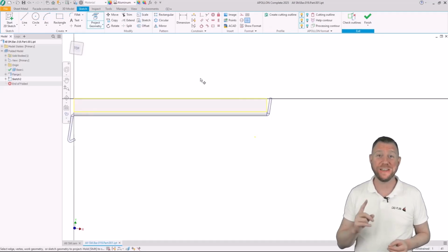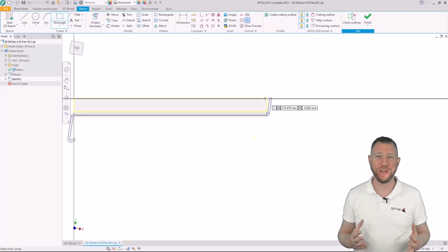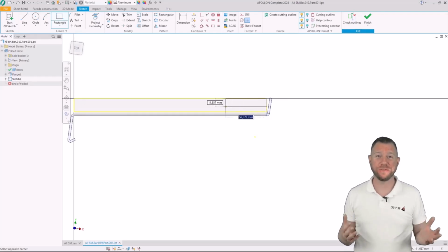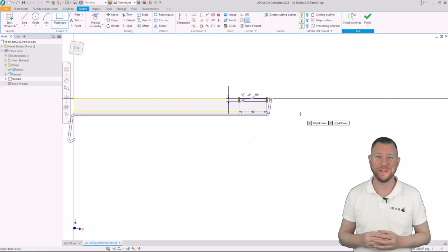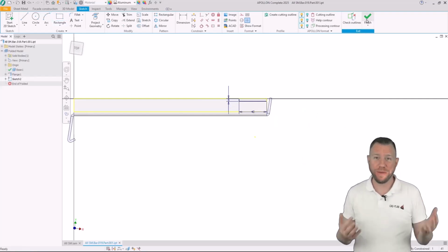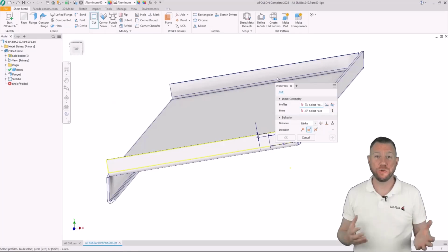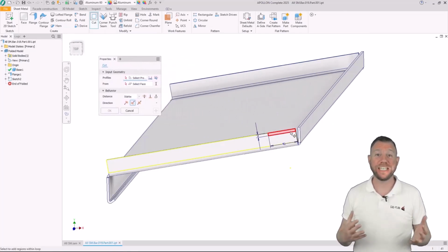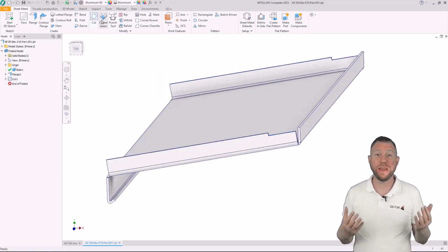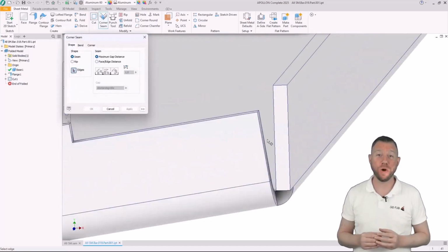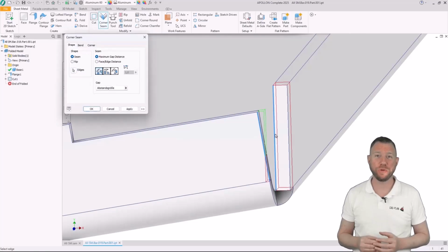You can see very clearly how easily and precisely we can work in the sheet metal design process. Individual editing steps can be carried out directly on the element and adapted to the structural requirements. In the next step, we create the notches. This ensures that the vertical profiles connect cleanly to the windowsill and that the cut parts fit exactly. These editing steps can also be performed directly in the model. This means that you always retain full control over the geometry and every machining step of the component.